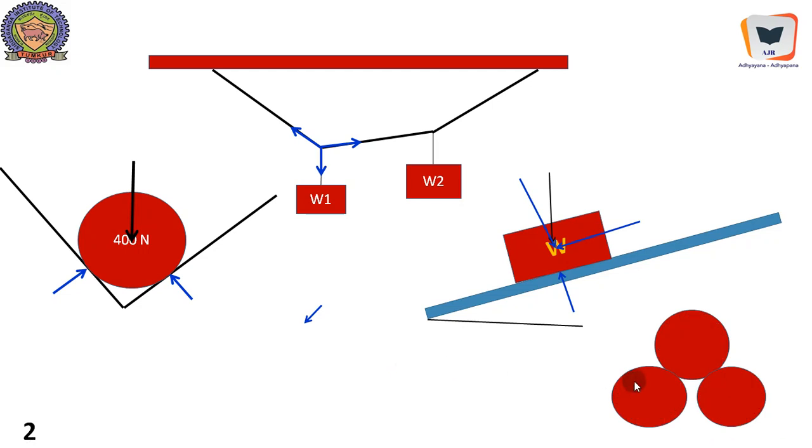The spheres placed will stand in equilibrium for a particular arrangement or placement. The weights of the spheres, here and here and here, three weights, form the active forces. Therefore, their resultant will be the sum of the parallel forces, the weight of this and the weight of this. If they were not supported one above the other, they would have been disturbed. Due to this self-supporting system, there will be reactions developed.